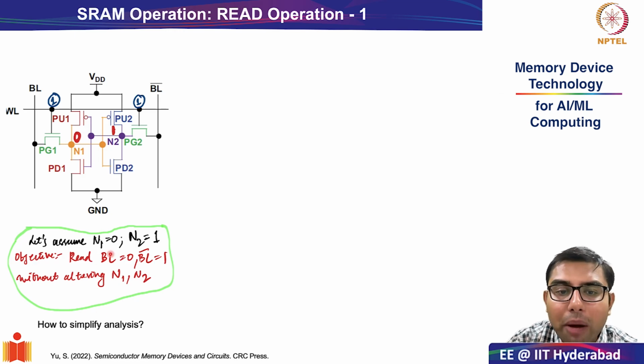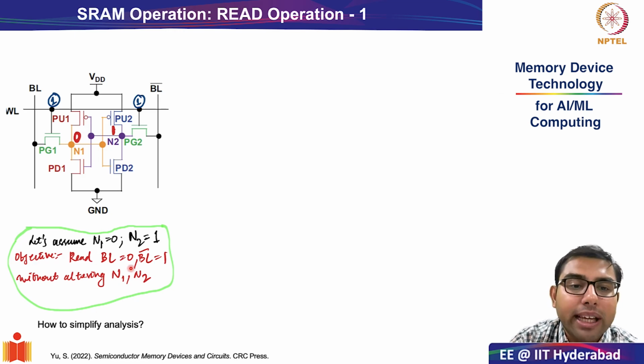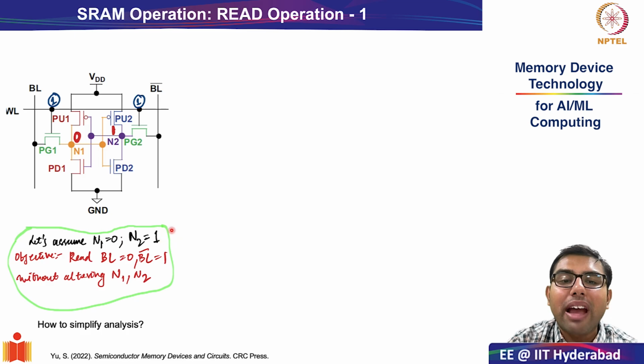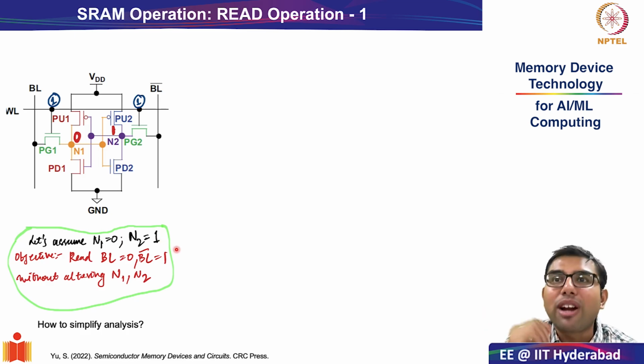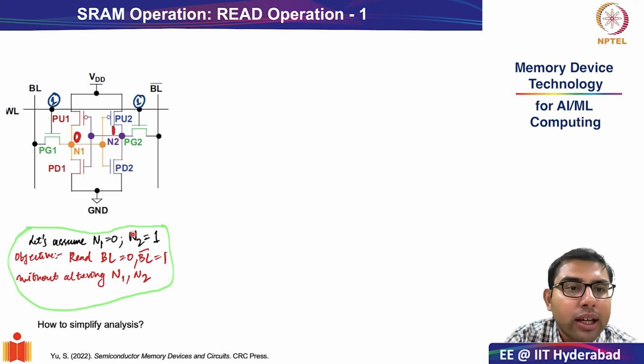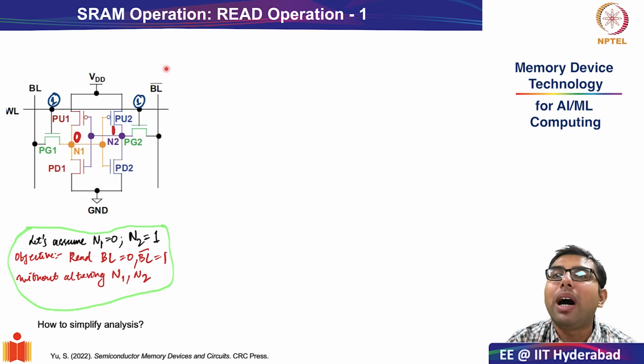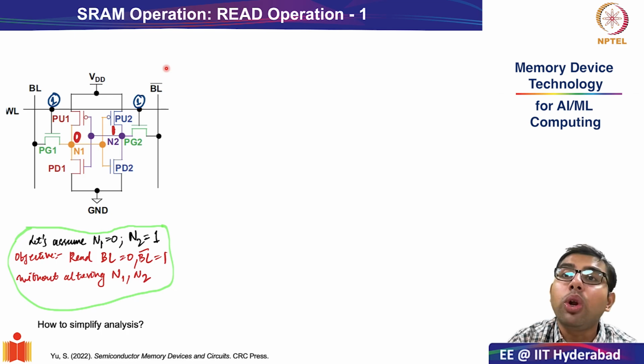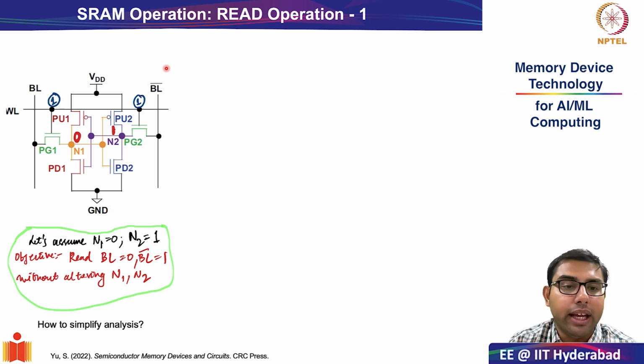So although we will not be able to see bit line equal to 0 and bit line bar equal to 1, as we had also discussed, a small analog voltage will develop. It is but natural to expect that the ends of bit line and bit line bar will ultimately be connected to the inverting and non-inverting inputs of a sense amplifier. So with this context, let us see how this read operation is facilitated.